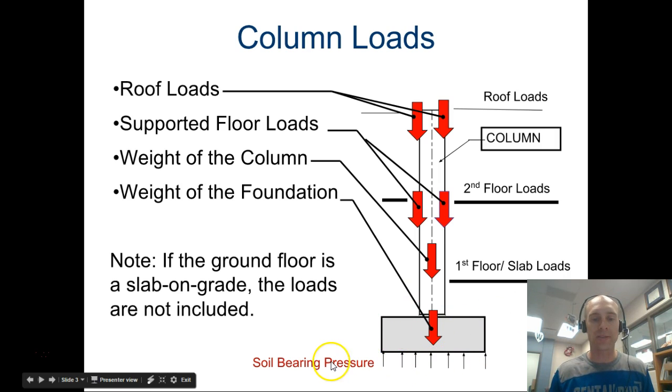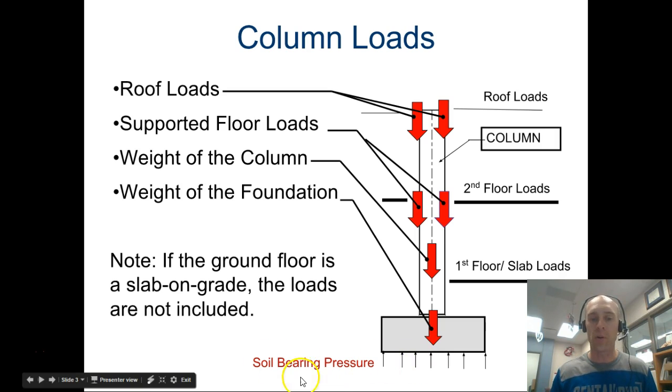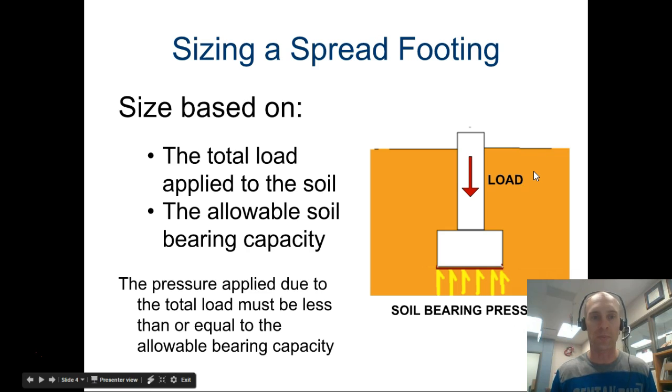The soil has a certain soil bearing pressure. It allows a certain amount of load before it actually gives, and that footing will sink into it. So you have to know what the soil bearing pressure is by doing a soil survey. You actually dig up some dirt and figure out how much pressure this soil can hold based on what it's made out of. Once we know that number, then we can figure out how big our footing has to be to hold this giant load. That's what structural engineers do.